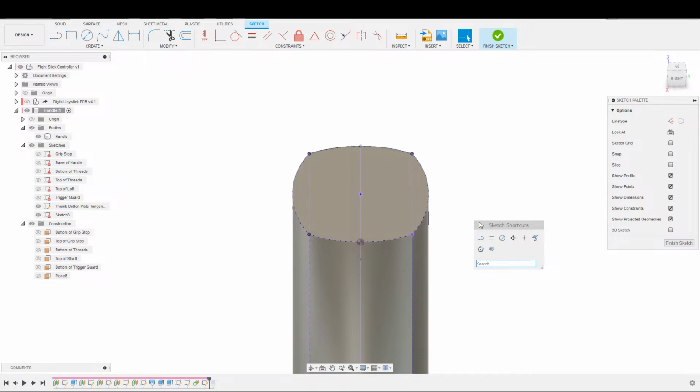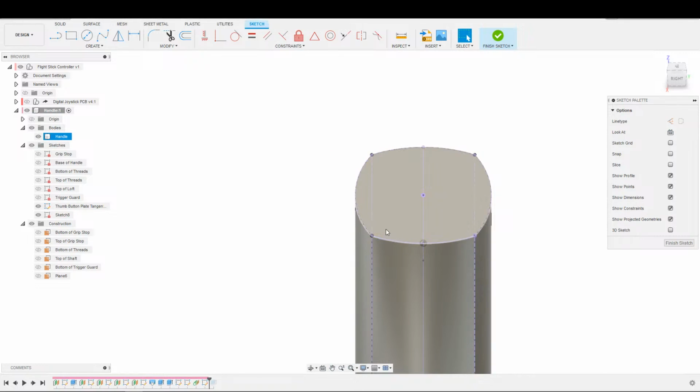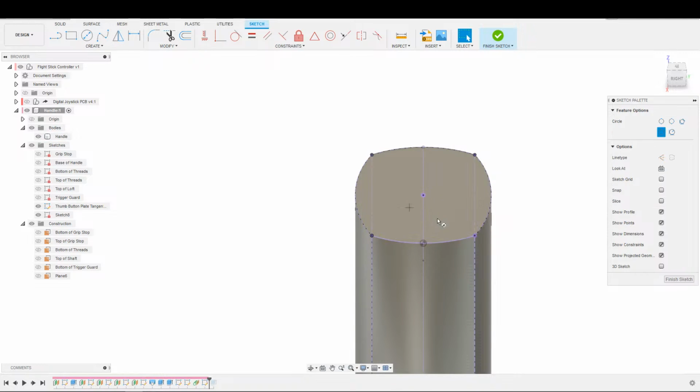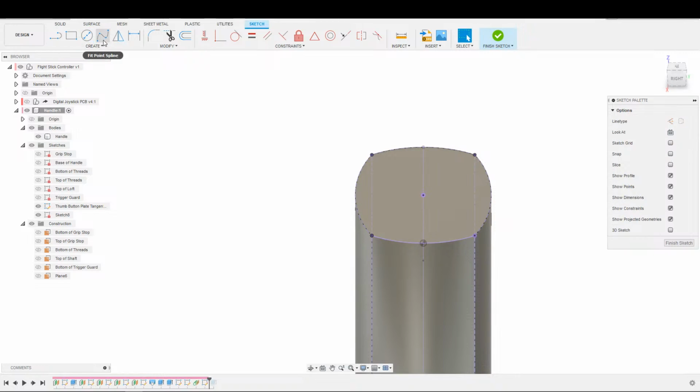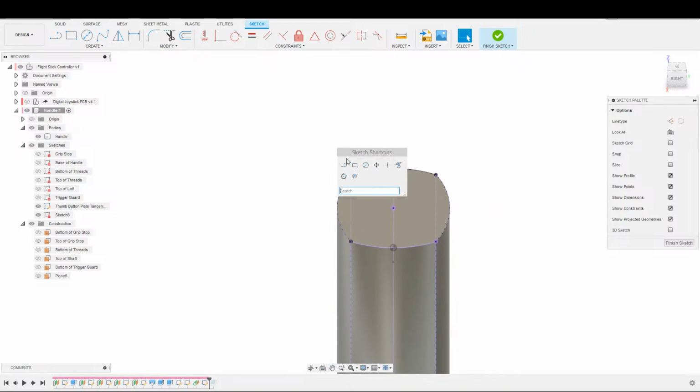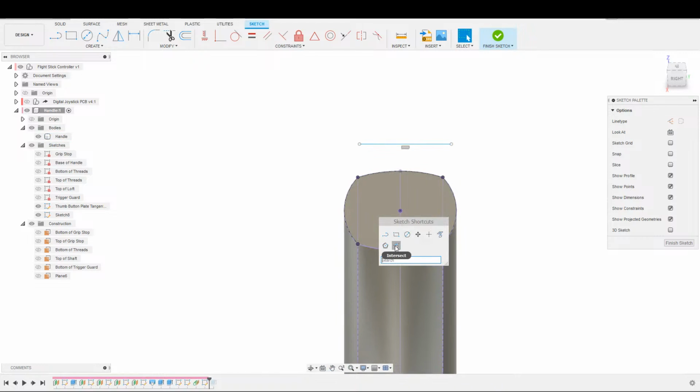And then, let's see. How do we want to build this plate? Actually, I guess I'll take this guy. I'll take that guy as my start, and then I will build the plate from there. That guy, I'm gonna put a flat top on it, I think. We'll grab the center point here, keep that perpendicular, make that to there.